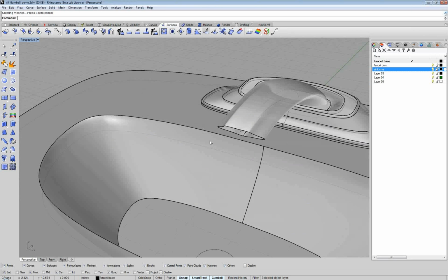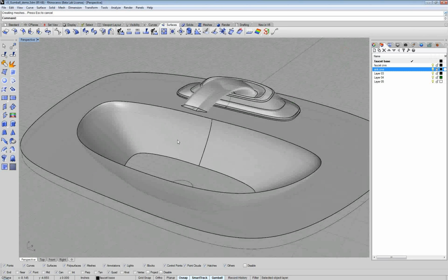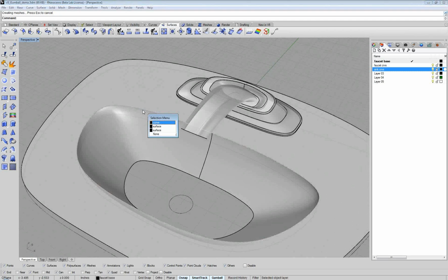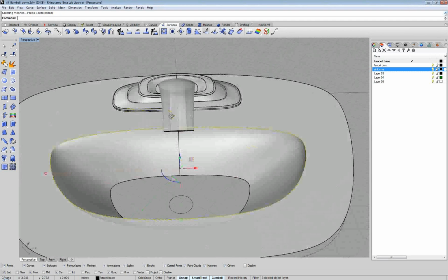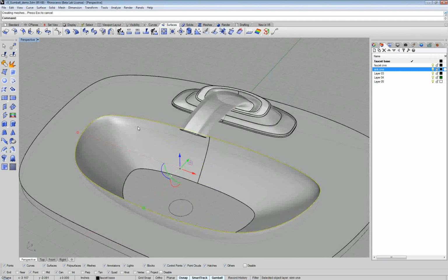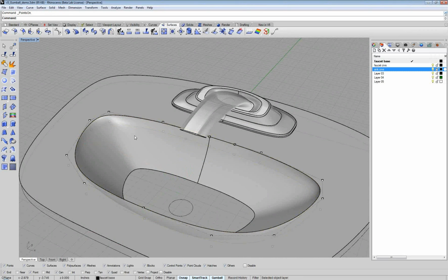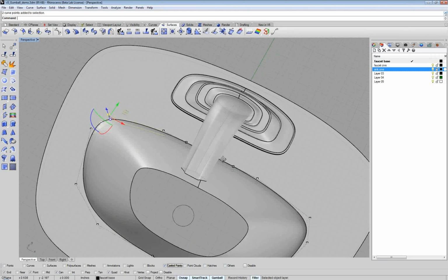And so now I have history enabled for two separate commands, and both of those commands are using this top curve, actually all of the curves. So I'm going to select those two curves and turn on the control points for it. OK. And I can utilize my selection filters again. So now I can start to customize the transition.